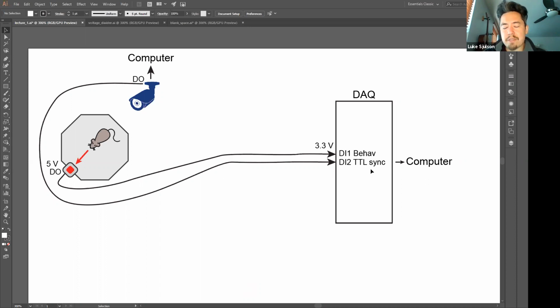And if all you're using is something like TTL pulses, then it can create problems, because you might not be able to align, say, a file that was interrupted in the middle based on something like that. But if you have an LED, then you can cross-correlate the LED video signal with the LED electrical signal that you've recorded here, and then you can actually realign those things. So that's an example of when having secondary synchronization methods is helpful.